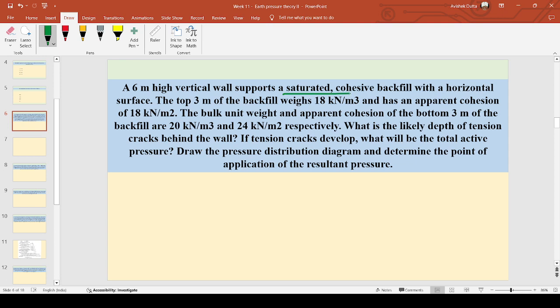Here you can see the angle of friction is not given, right? Yes, Abdul, you can speak. Yes, sir, assume as 0. Yes, yes. Okay, I think your mic is not working properly. Yes, angle of friction will be equal to 0. So the first thing I'll write over here is the angle of internal friction will be 0.